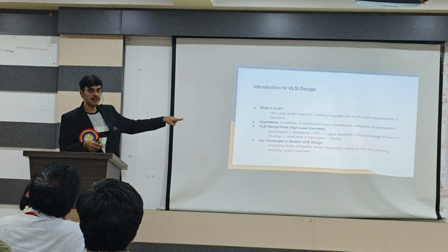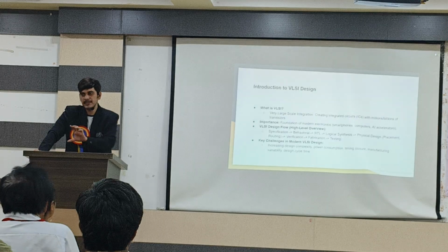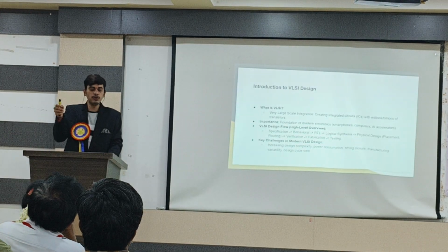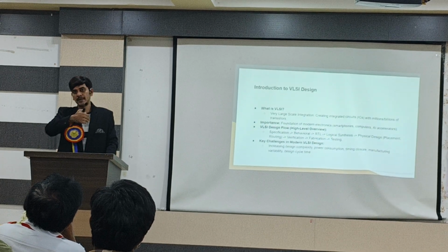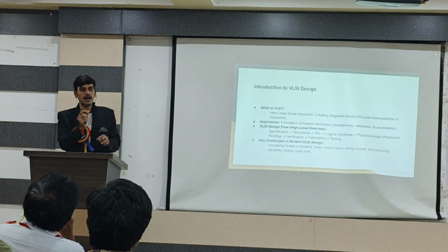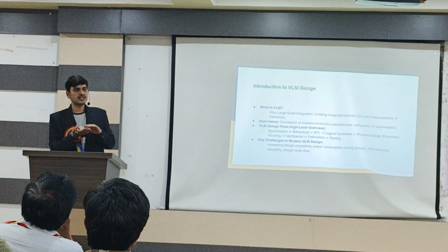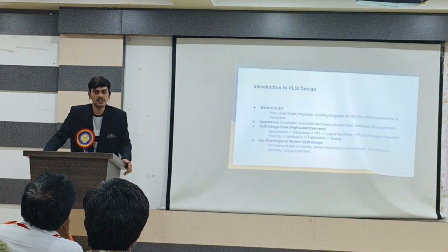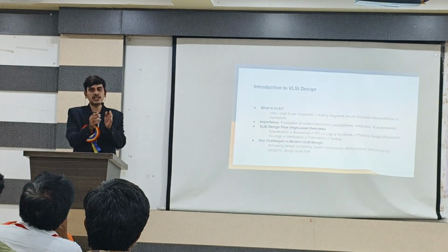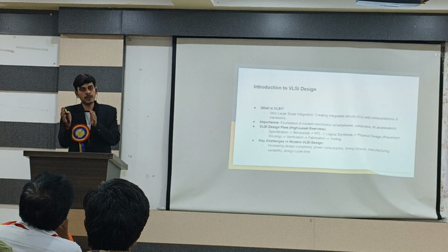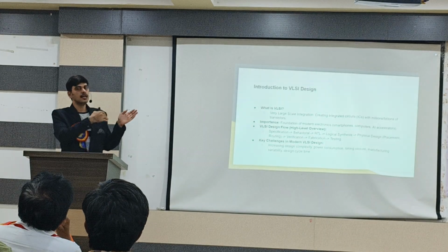From there, for physical verification, we have DRCs, design rule checks. You have learned about masking for photolithography, the process to fabricate a chip. The transistor gates are all going to be fabricated on the silicon. TSMC and Samsung are two major foundries, and TSMC is a major player. These guys will provide you the DRC rule checks, like these transistors should have a certain distance and width and there should not be crosstalk. From one bit to another there should be spacing. These kinds of rule checks will be given by the foundry.